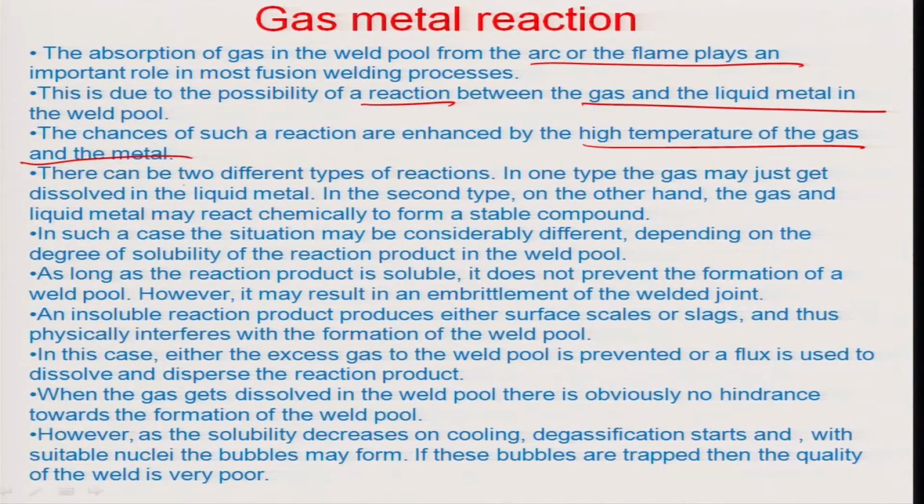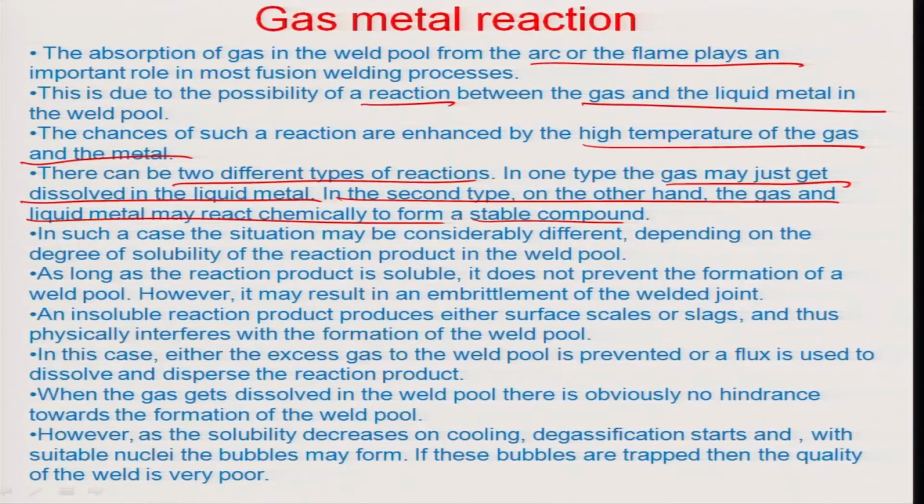So, there are two different types of reactions which happen. In one type, the gas may just get dissolved in the liquid metal. So, this is more like a physical phenomenon, physical dissolution, which may lead to weld defects or certain holes, pinholes. In the second type, on the other hand, the gas and the liquid metals may react chemically to form a stable compound, and this is even more dangerous because the strength of the joint may fall down because of formation of such chemical compounds. So, in such a case, the situation may considerably be different depending on the degree of solubility of the reaction product in the weld pool.